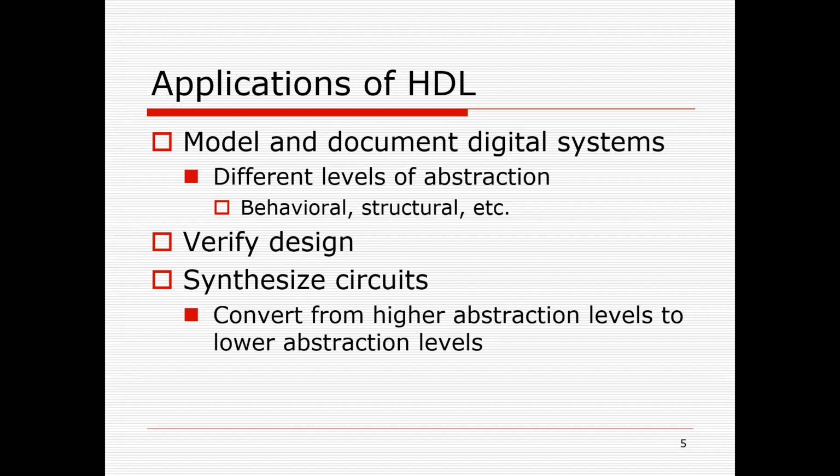So what are the applications of HDL? You can model hardware, and you can document hardware in that language. The language also helps you to document, so you don't have to create additional documentation for it. There are various levels of abstraction. You can design only a behavior, where you state how outputs behave with respect to inputs. You can also define its structure, for example, which gates to connect where, the netlist to realize a particular functionality. You can also have a data flow model, where signals propagate with time. And you can even have a mixture, combining any two or all three.